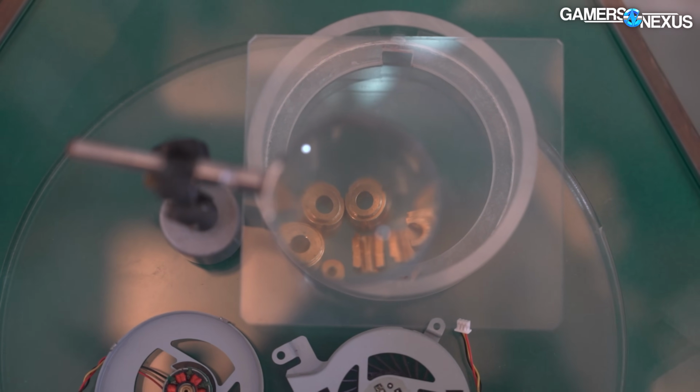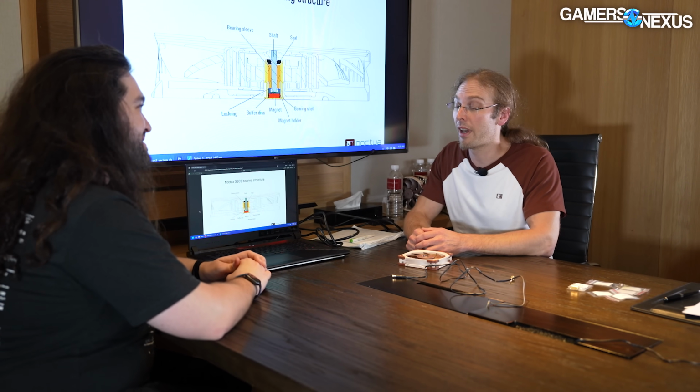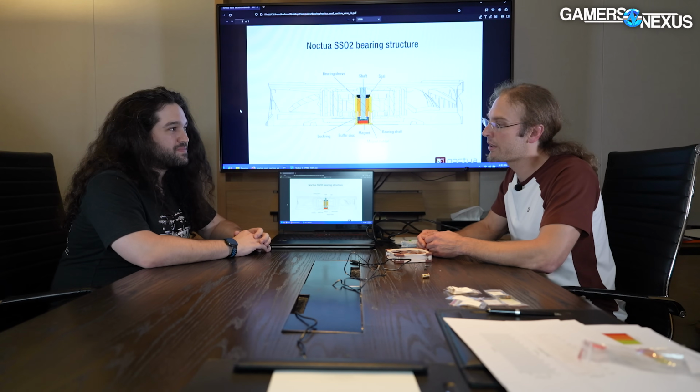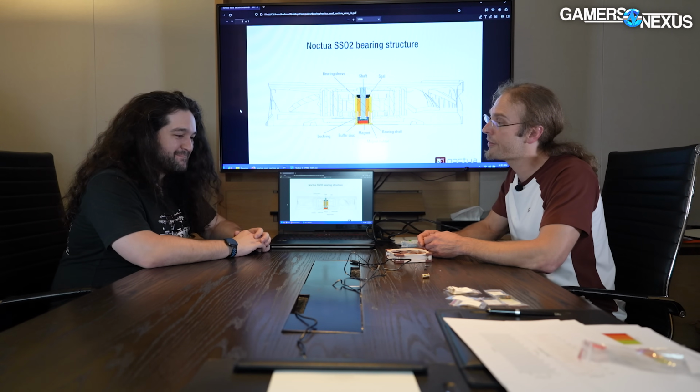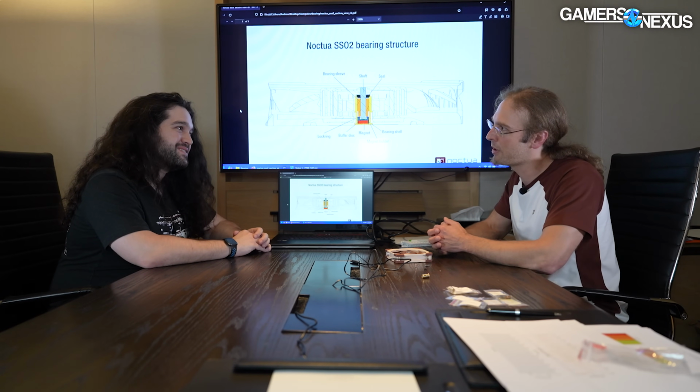You could look at the MTTF or MTBF specs manufacturers give. If they're honest about them. But there are so many different ways of establishing them that they are utterly uncomparable. And you also see numbers floating around, like if you see 300k hours on a fan, it's more than 30 years. I'm not saying that this cannot be calculated, but the problem is if you take a, let's say, 3-4 month accelerated lifetime test and then extrapolate to 34 years, that's a lot of extrapolation.